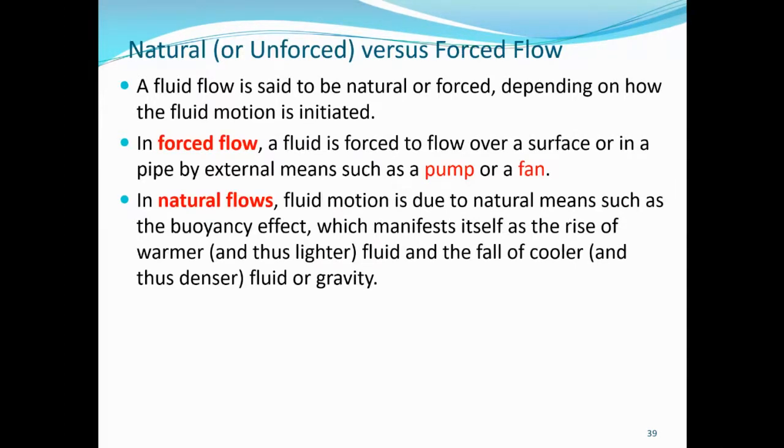The buoyancy manifests itself as the rise of warmer and thus lighter fluid and the fall of cooler and thus denser fluid, or gravity. We also discussed the hot air balloon, in which you heat the air. When you heat it, it becomes lighter, so it flows vertically up. The buoyancy effect will push it up, and you maintain your level by maintaining the density of the air, by maintaining the same temperature inside the balloon and outside the balloon, because once the temperature is the same, they will have the same density.